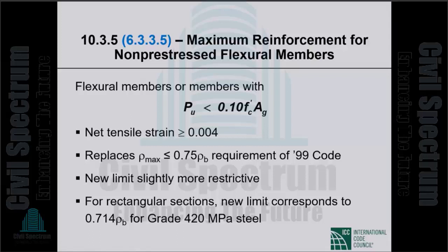We are not saying all flexural members have to be tension controlled, but we are saying that the net tensile strain cannot be any less than 0.004.